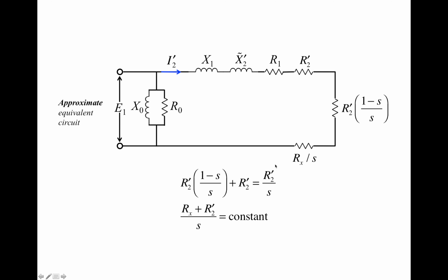If Rx can be varied automatically in such a way, then the current will remain constant because the resistance is constant, and the voltage is not going to change. So there is no danger of burning the generator, even at very high rotor speed. If the rotor speed is very high, we just make Rx high enough so that this ratio stays constant. In this case, we can keep the amplitude of the current within a fixed bound, so there is no danger of burning the generator.